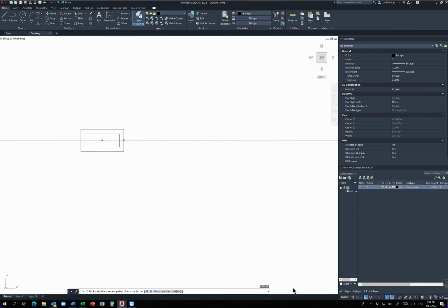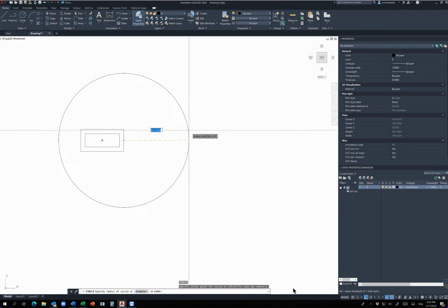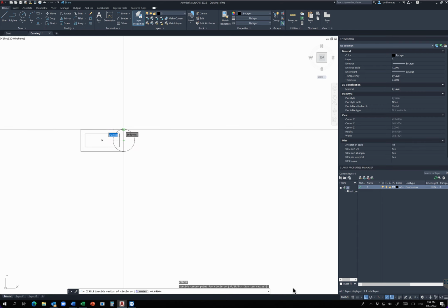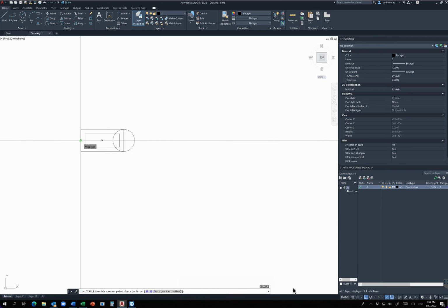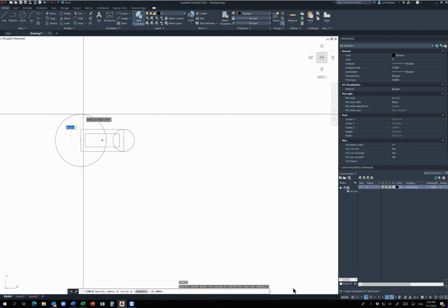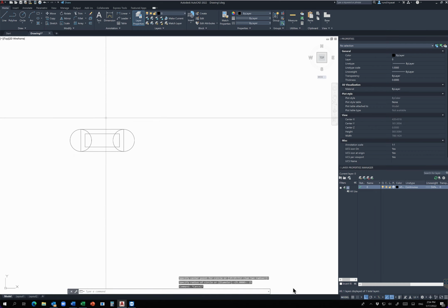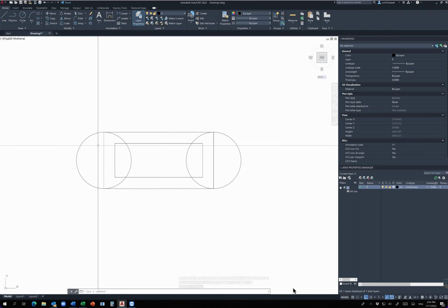Right now, I'm going to choose this to be the center point of the circle. And then it says specify the radius. So if I know the radius, this is where I input it using my keyboard. Or if you know the next point, then you can simply click on the next point and it will automatically be drawn. That's it. It's as simple as this. I'm going to draw the circle again with the radius, so I know the center point is here, and say I want the radius to be 25 units. So I'm going to type 25, hit enter, and that same circle is drawn. I only place different inputs and different prompts to the command line to draw my circle.